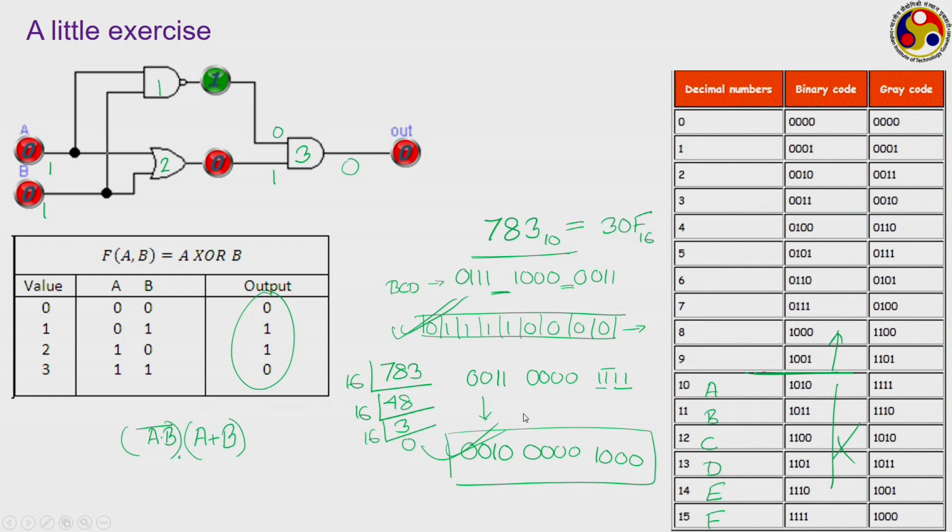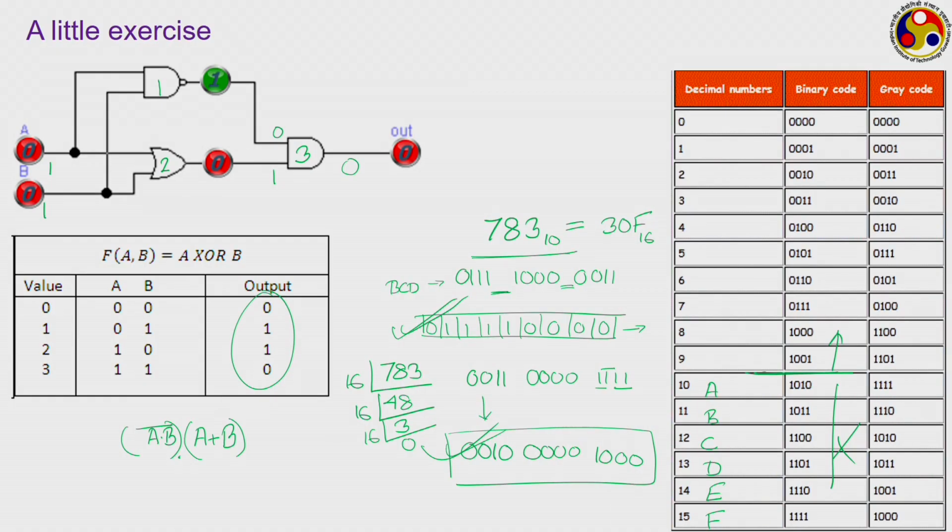Depending upon in which format you are storing the number, the same will go to the register of your computer or in the memory of this. So, we know now how to convert a decimal number to its gray or BCD equivalent and store that in memory. But numbers are not all, rather there are several situations where we have to deal with other characters also, and that takes us to the next one, which is the alphanumeric code.